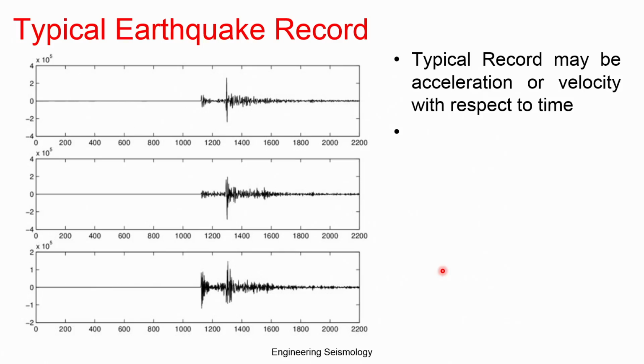The seismic record, as we have discussed, will be a single component record or a multiple component record. Multiple means like 3 components generally they use. The 3 component record basically implies that one component they orient as a horizontal component towards the north direction. So, the north south is one of the components, another one is perpendicular to that, the east west, and the third one will be the vertical component. So, this is basically a typical earthquake.